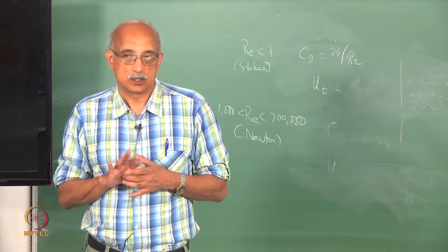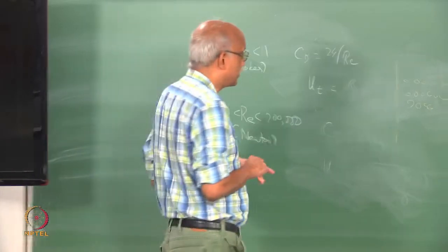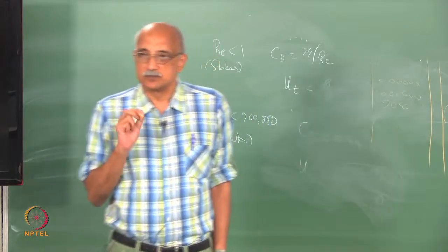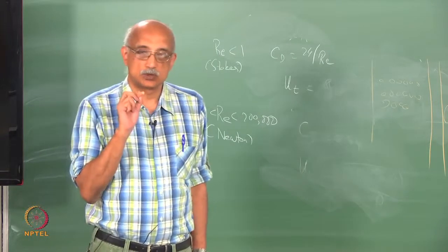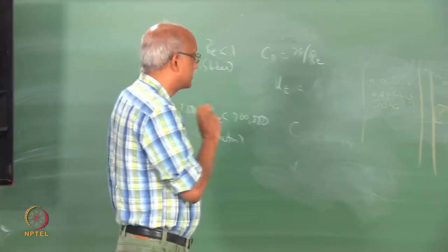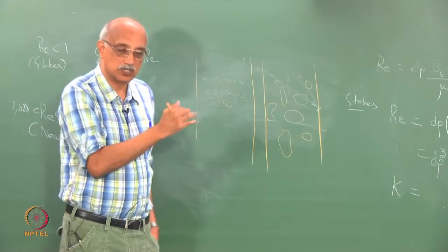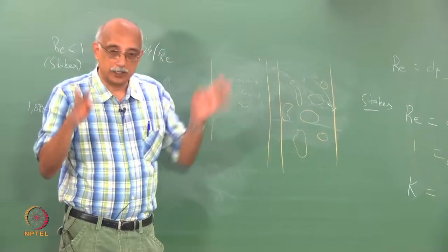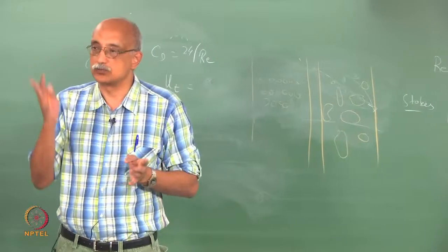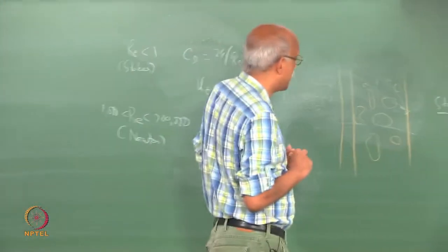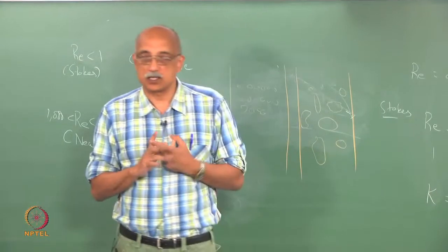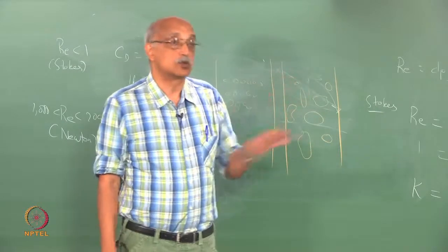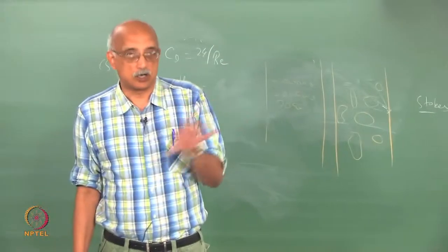Spherical? Actually, it turns out that a perfectly spherical particle can only have point contacts, right? So if you shake this and allow the particles to settle into a stable configuration, and then you look at the void fraction available for fluid to flow through, versus one in which you have a variety of shapes, it's interesting that in a majority of cases this configuration actually settles in a much more cohesive fashion, because it's kind of more accommodating in a way.